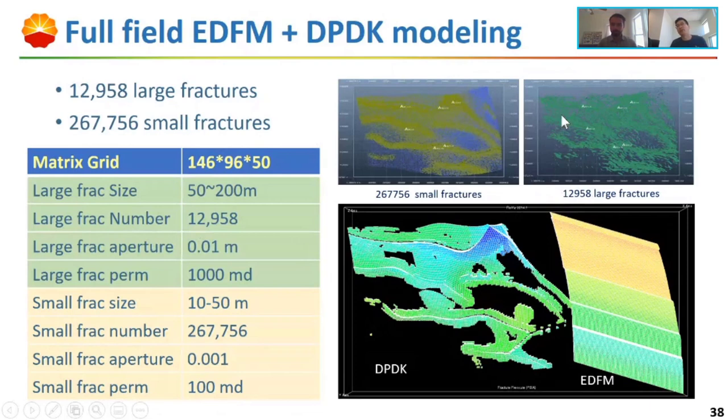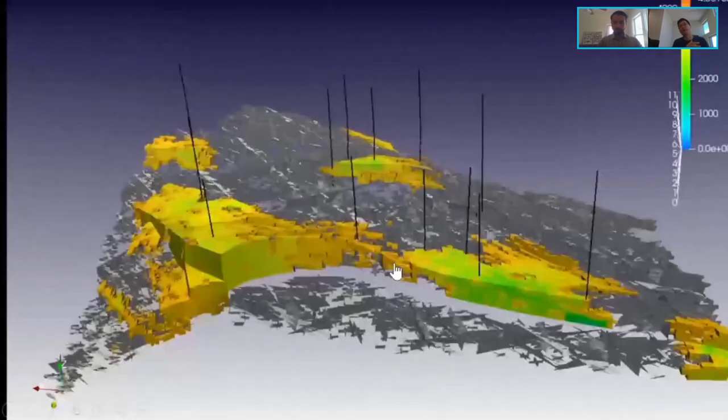After we do the reservoir simulation, we can see this. In this clip, you can see a process that quickly shows what model we have and the reservoir fractures. And then here you can see we got the pressure response in 3 dimensions, and you can see exactly the fractures' pressure response. And also we can cut through, see the fractures and the drainage area, and we can look into that to calculate the drainage area or maybe the related EUR or something.